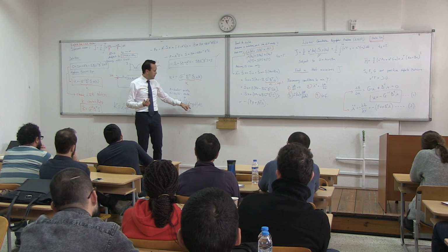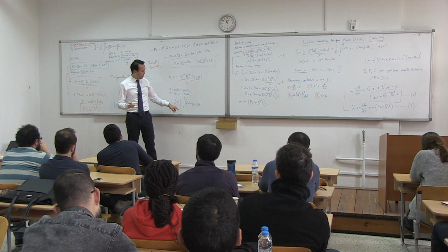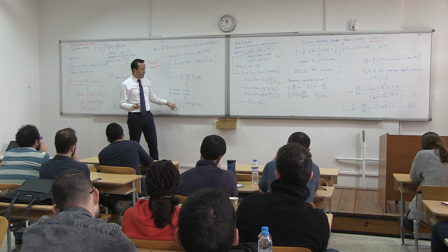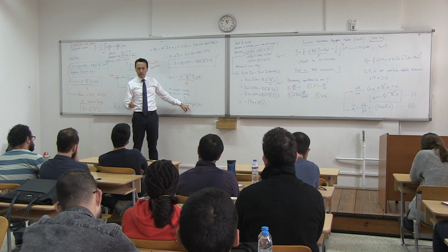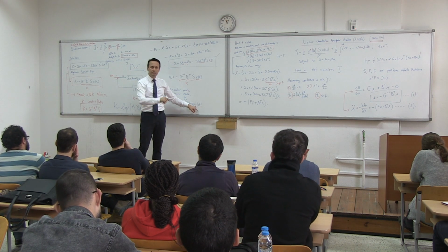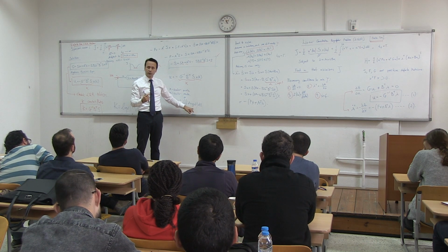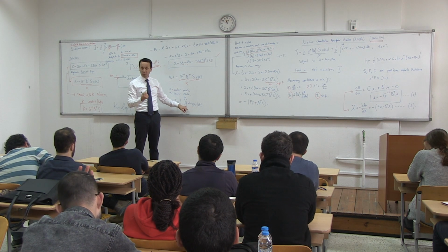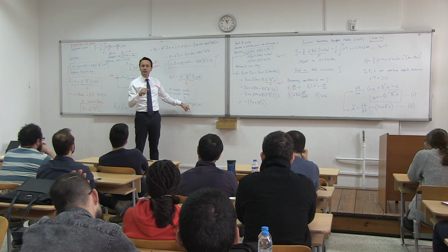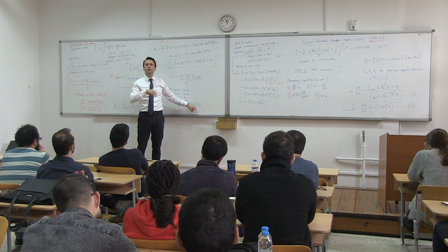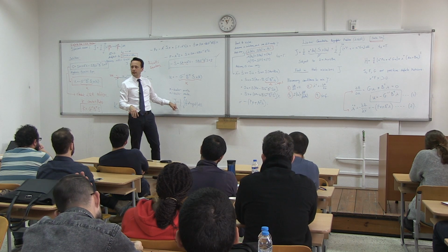And the same amount of change in u, because it's multiplied with 0.1, would have a small effect on J. So if I want to minimize J, the problem will try to minimize x as much as possible compared to u. Because u can be 10, then it will be multiplied with 0.1, then it will be equal to 1, this part. But if x is 10, it will be multiplied with 1000, so it will be 10,000 over here. So meaningful would be to minimize x to 0.1, and u can be 100, doesn't matter. And it would still minimize J. Does it make sense? No.